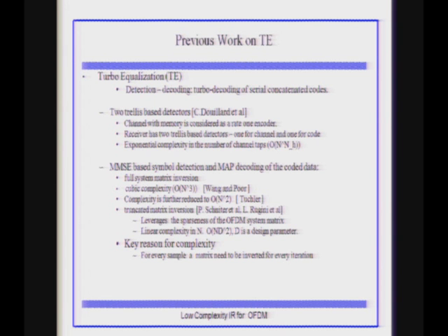I mean, the receiver, and so we get an MMSE estimate of the symbols, and it has been done iteratively, and you will see the details soon. So the complexity came down from exponential to cubic because, as we will see in the coming slides, a matrix inversion is involved.